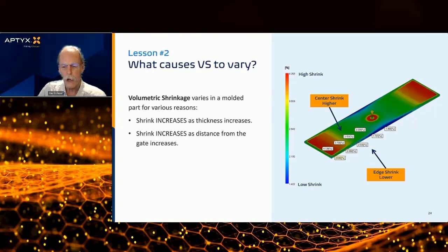But what I want to point out is the piece of information that I never really understood. And when I did, it started to change things for me, and that is edges. There's an edge effect that's way different than the center of the part. You can see that here. You can see that the edge is shrinking at about 1.4%, and as you go down that edge, you get as high as 2.6. But it's significantly different than the center.